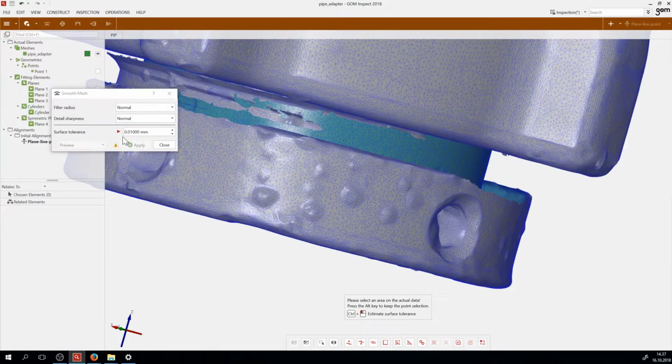Smooth is again a bit of a dangerous tool, because it will again be distorting surfaces, but sometimes if you have a very rough surface and you want to build some things and you're having problems, you can use this. Or if you have some dirt, like small dust that is giving you problems, you could also use that. So let's see if it's going to work on this.